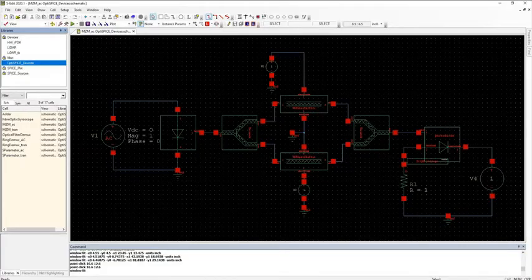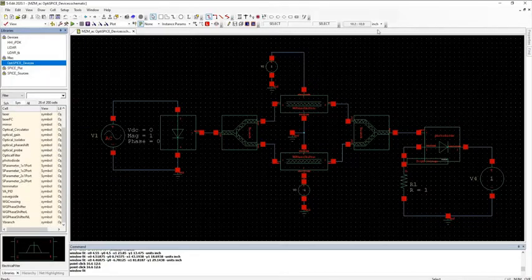On the left side, you can see the symbol library for OptiSPICE. This symbol library includes a set of basic building blocks that can be used either standalone to build prototype circuits, or they can be used in the test bench when you're extracting your netlist from the LEdit layout. In the schematic, you see these building blocks used to create a Mach-Zehnder modulator device. And these devices are also combined with standard SEdit devices.